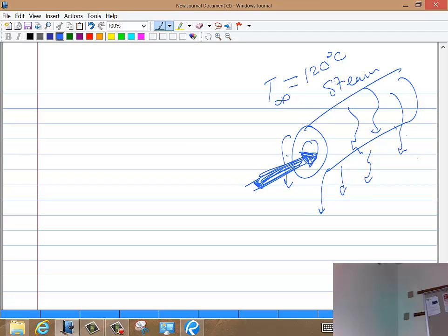Why is it so far away from the actual power plant? You tell me. Well, you would like to use very cold air, right? And the power plant, the boiler is probably hot. So it's like you don't really want the exhaust of your kitchen to be near the HVAC condenser, right? You want it to always have fresh or cold air near the condenser. But it's not that far away.